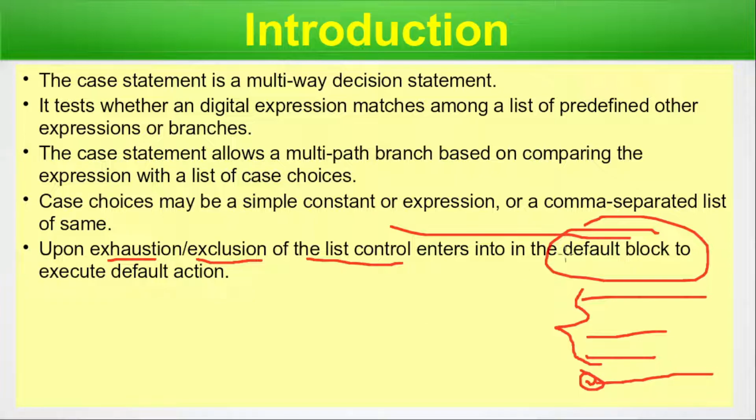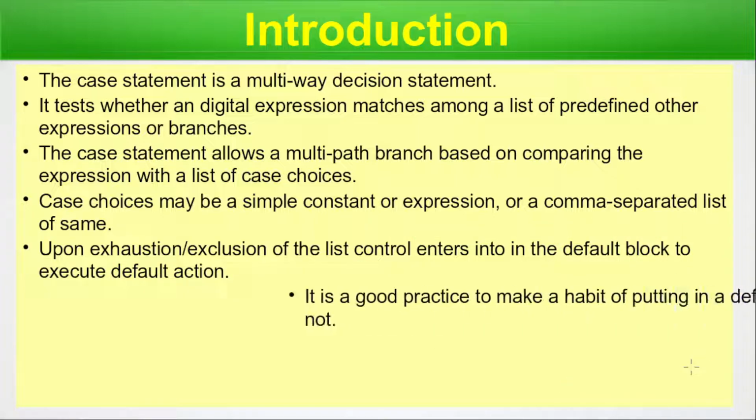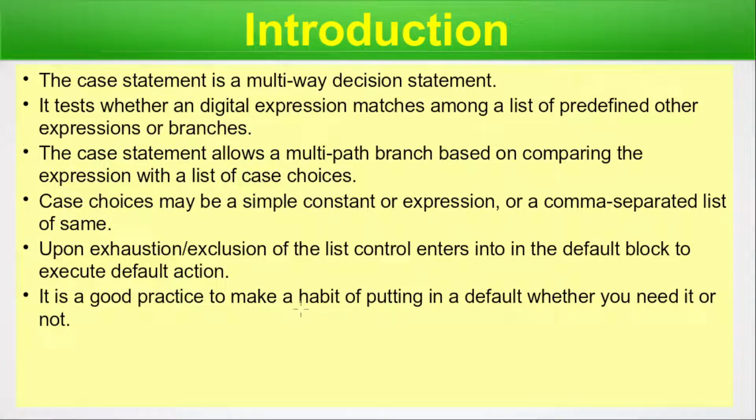And once it enters the default block, it executes the default action specified using the default statement. It is a good practice to make a habit of putting a default whether you need it or not. This is very, very important because in Verilog, you might have to debug your code based on different case scenarios. And in some particular case scenario, say your expression is not matching with the values that you have defined